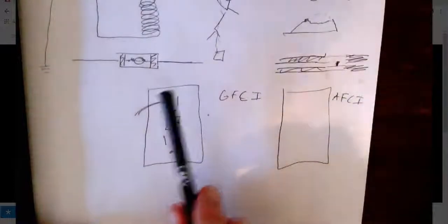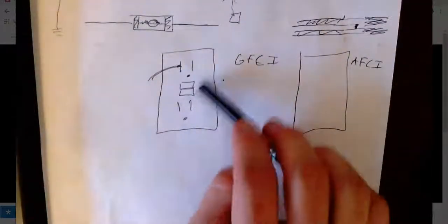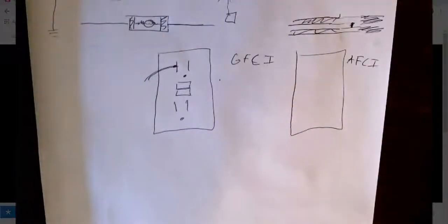conductor. So a regular circuit breaker, that I showed you in the video, you'd be long dead before those things trip, basically. If those things trip because you're getting electrocuted, you're pretty much toast. So these things are because they're like 15 amps, and probably 2 to 5 amps will kill you. So, well, you're just bad resistance. Anyway, these guys are providing safety in a different way. So that's why you have those.